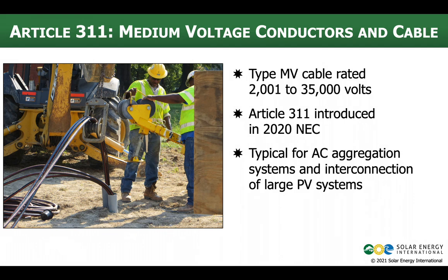The inverters are putting out through a transformer something between 2,000 and 35,000 volts, and we're running medium voltage around to those transformers to pick up all of that current. Something that we do see often done. Well beyond the scope of this class. Just keep in mind, the takeaway here is if you are getting roped into sizing medium voltage conductors, you didn't learn enough about it to do it here, and there are differences. So really just want to make sure that people are aware of that.